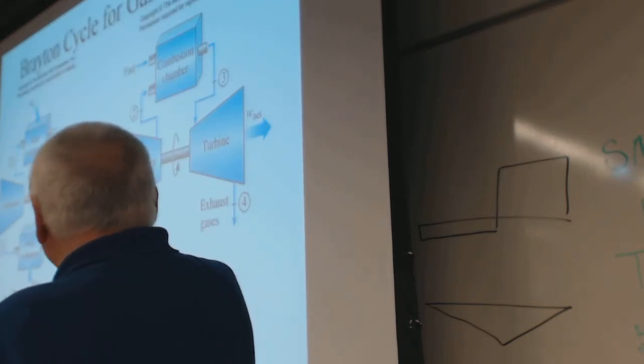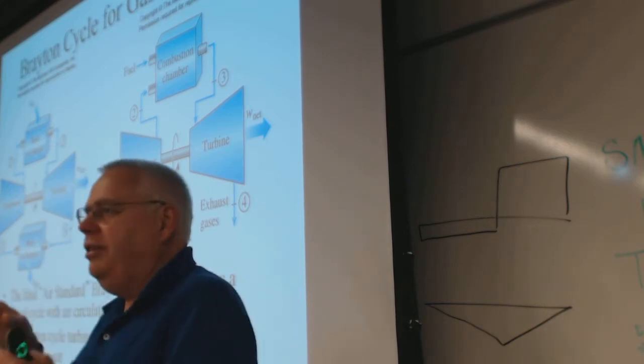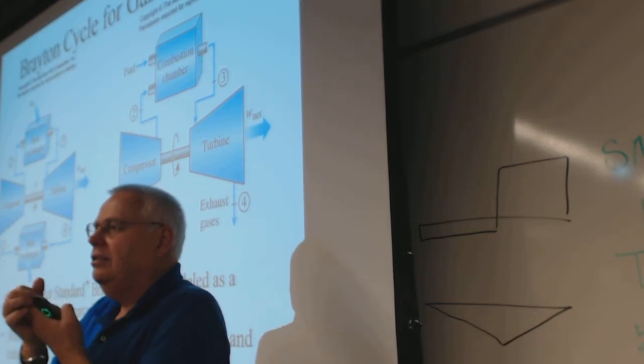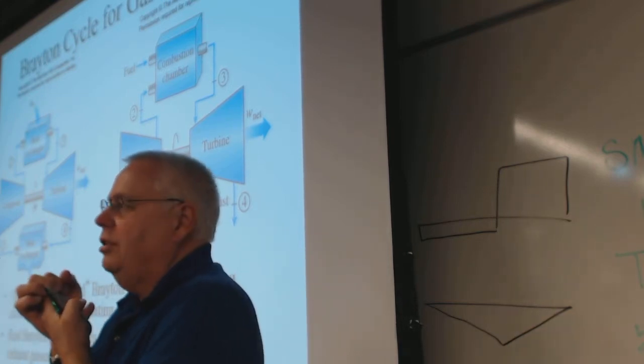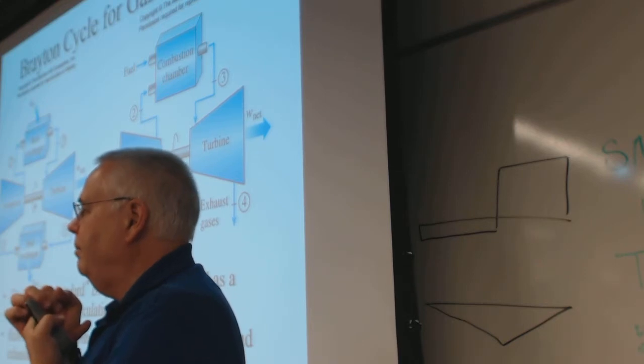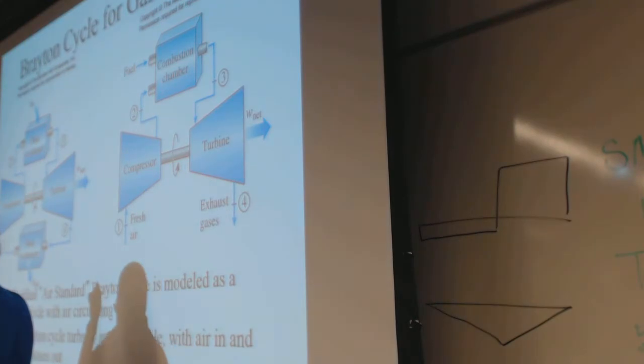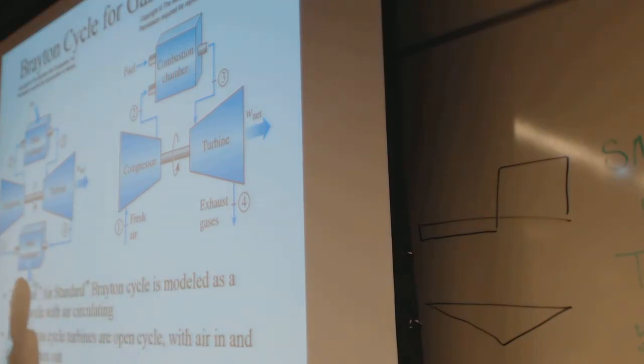The Brayton cycle is different. All three of these, the Otto cycle, diesel cycle, Brayton cycle, are all ideal gas. So we're all using the ratio of volumes or pressures to some exponent with the k in it. And if you've got an exponent with a k in it, you're doing an isentropic analysis. And this air, the idealized, we're talking about air standard, just to simplify things. It's that air goes in, air goes around, and it's a closed cycle. So we have air,